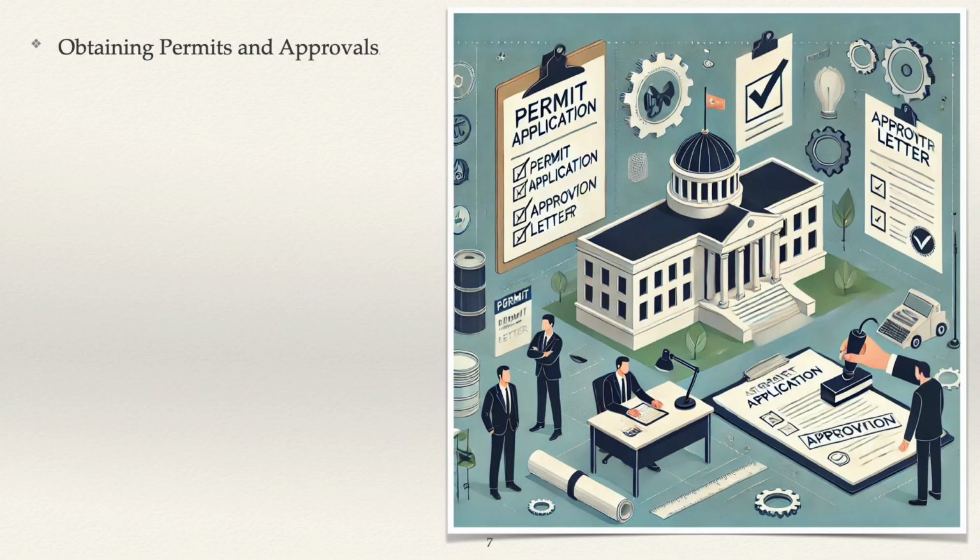C. Road use and access permits. Road use and access permits are required when project access roads intersect with public roads or highways. These permits ensure the safe movement of vehicles and help prevent traffic disruptions. In particular, the contractor must obtain permits for the following scenarios: using roads during the heavy movement of equipment, crossing highways with machinery or construction activities, establishing temporary stores or camps near state highways, especially if they affect road activity, implementing signboards, or making modifications to roads for construction purposes.